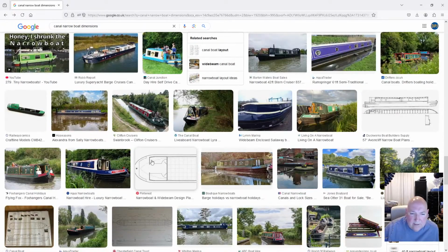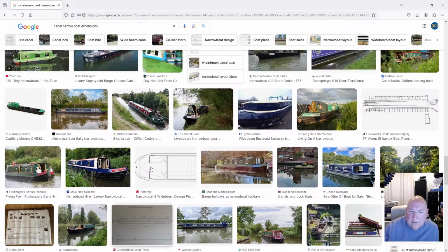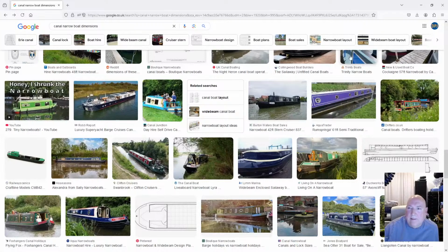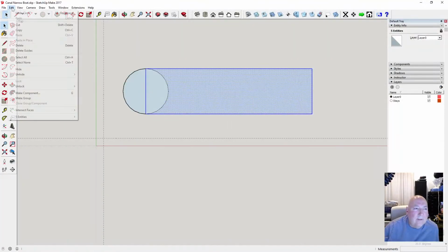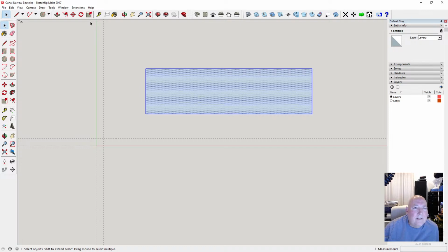Yeah, it's a bit more narrow there, and it's not quite like a circle, is it? Yeah, it's got a bit of a weird. So right, okay, fair enough. So we don't want a circle. So let's tell you what we'll do. Let's come out here. So we know we've got 60 mil. So to come half of there, I'm going to say 40 mil. Come out a little bit more than normal. And I'm going to stick a line at 30 mil. I'm going to put an arc in from here to there, and I want to come out sort of like that at a known reference.